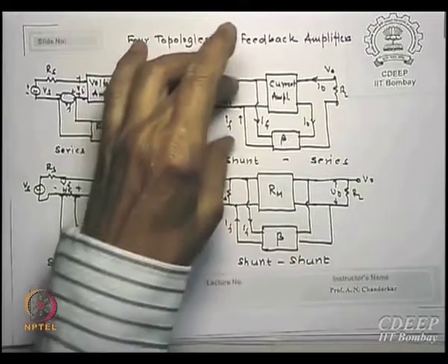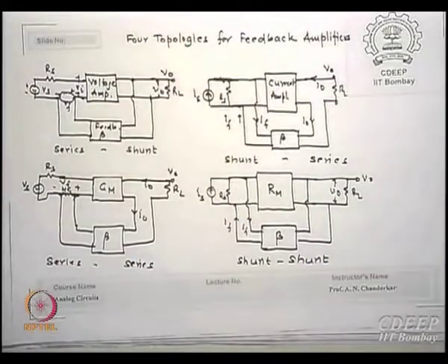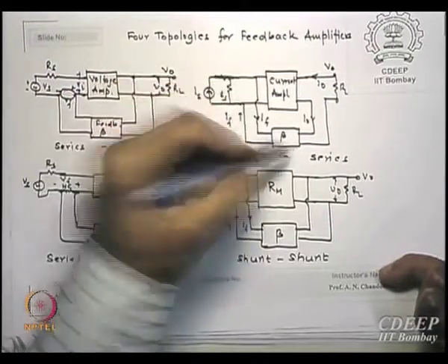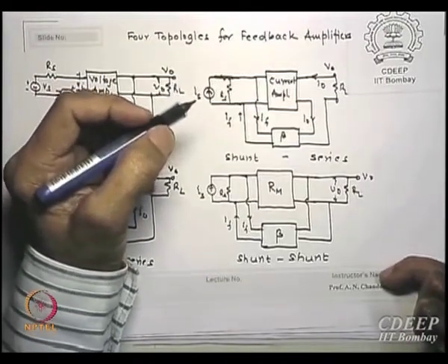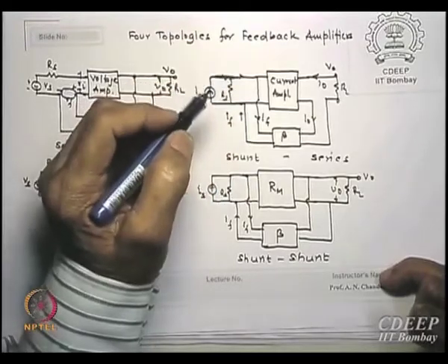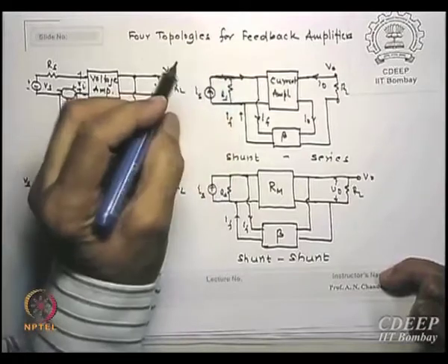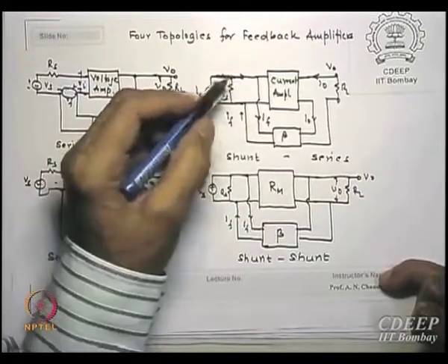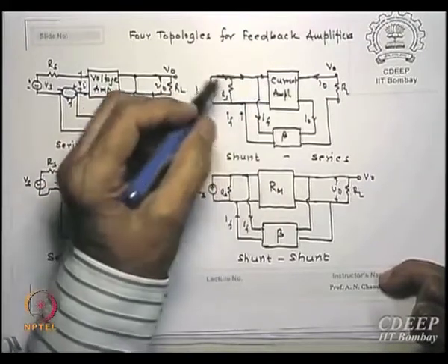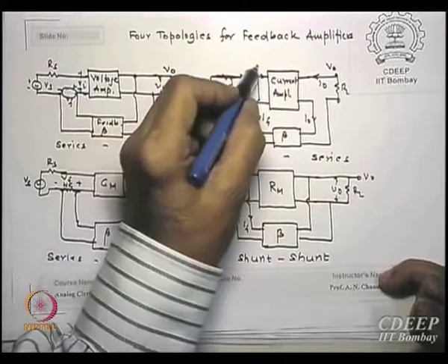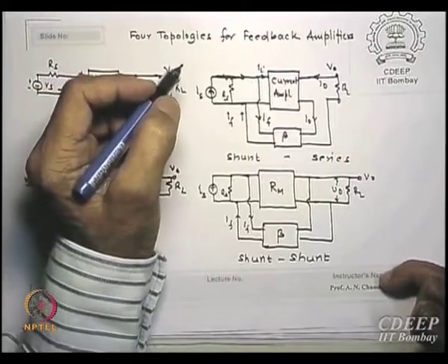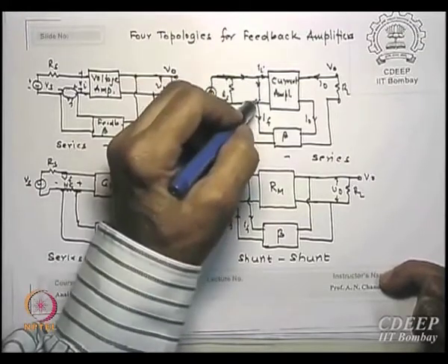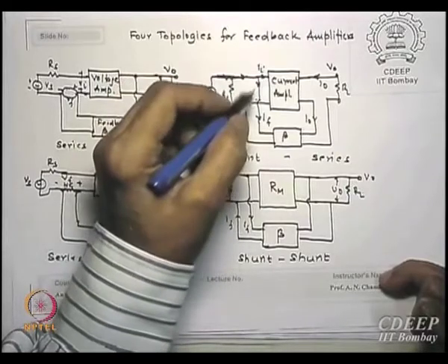So you can see the way I have fed. Which is the path for the feedback current? It goes like this and comes like this. So this is essentially shunting the current at the input. Remember what is being entered here? Current. This is a current source. I am entering a current here, and that is getting modified by this current source, which is the feedback current. So what is the Ii current here? Can you tell me now? If this is opposite phase, Is minus If will be the actual current Ii flowing inside the amplifier. If this current is leaving and this current is entering, then Is minus If is whatever is going to the amplifier. So if If increases, what does that mean?